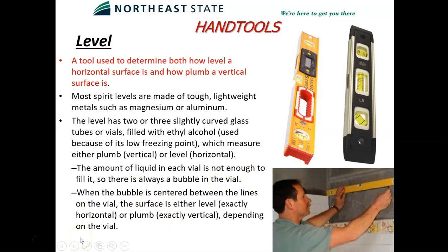Not a whole lot to talk about with a level. You've got a bubble in it. You line up the bubble with little black marks and determine if it's level. One thing you keep in mind though is your bubble always goes to the high side.